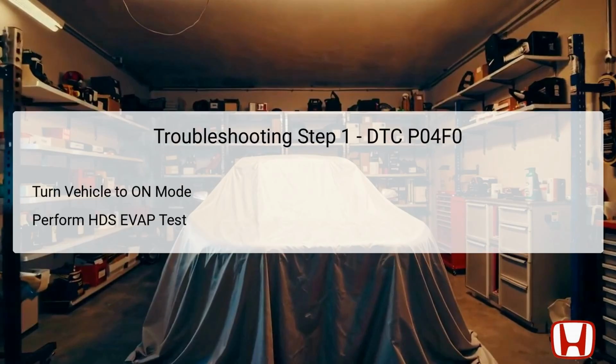Begin the troubleshooting process for DTC P04F0 by turning the vehicle's ignition into the on mode without starting the engine. This allows access to the vehicle's diagnostic systems. Then, utilize the Honda Diagnostic System, HDS, to select the EVAP test and proceed with the function test.